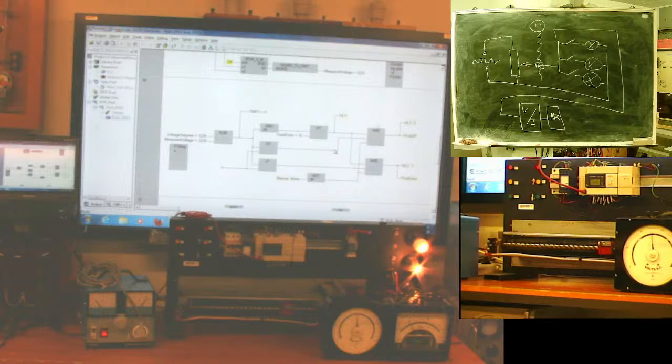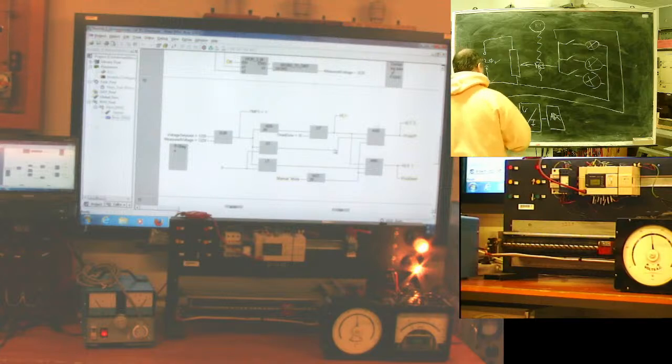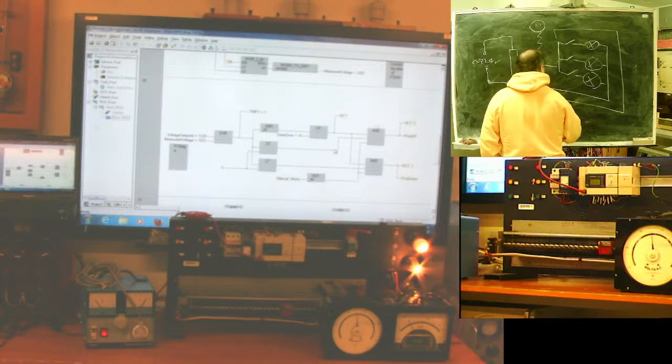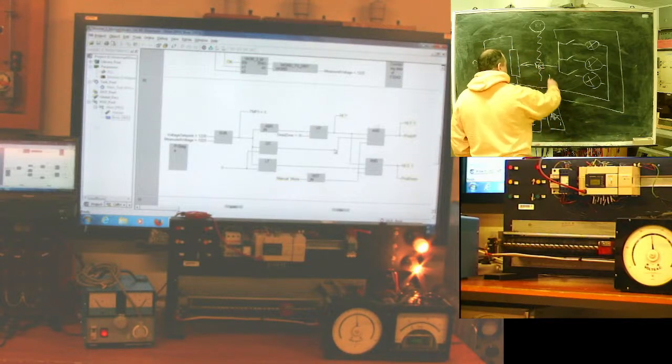In simple words, it's a voltmeter, producing voltage or current in relative values. It produces an integer from 0 to 32,000, something like this, proportional to input current. It has 2 channels, ADC1 and ADC2.